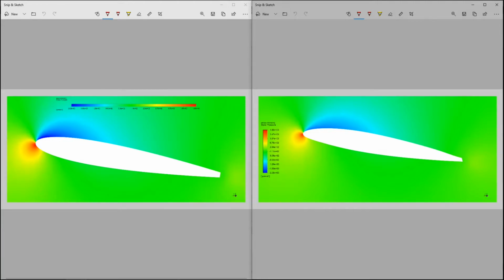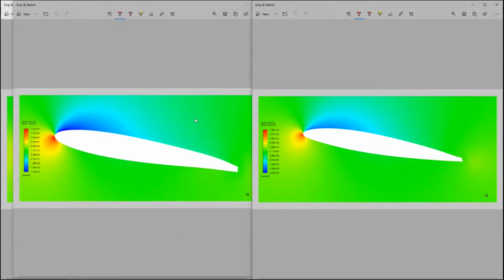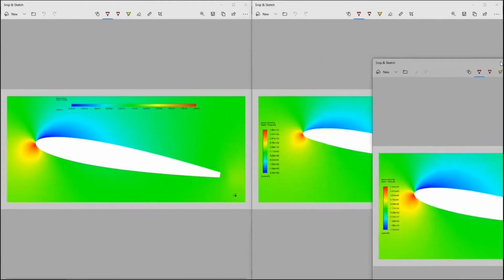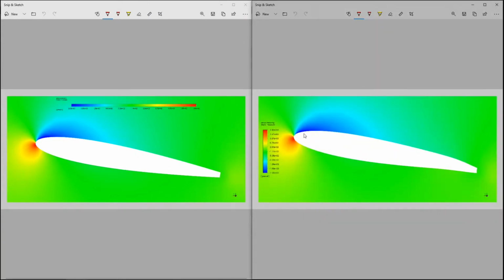This one I've actually maximized for just thrust as well. So let's look at that one. You can see here a bit more of a drastic change between the start point and this one, in terms of a much darker blue. And then this tilted down trailing edge keeps the flow attached, I assume, for longer.